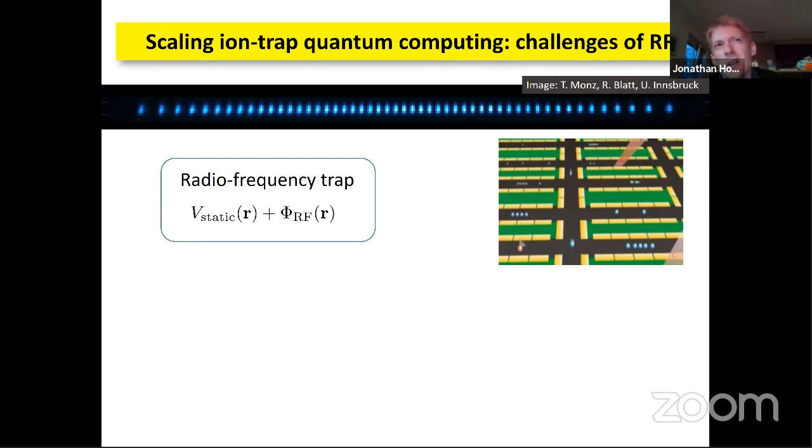I don't think we see the chip particularly heat up while we're using it, but then we're battling other things. Our particular problem is that, as I said, ions are sensitive to charge, and when you put light through glass structures, it moves charges. Now there are a few tricks we've played to get rid of that. The first order thing is that we try and keep the silicon as a ground plane, but of course silicon is a semiconductor, and when it's cold, it's pretty much insulating. But if you put light in, then it starts to activate charges.